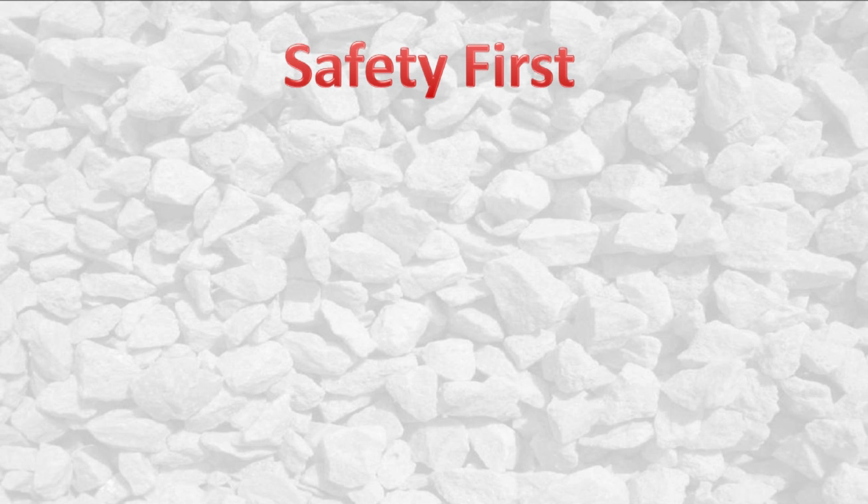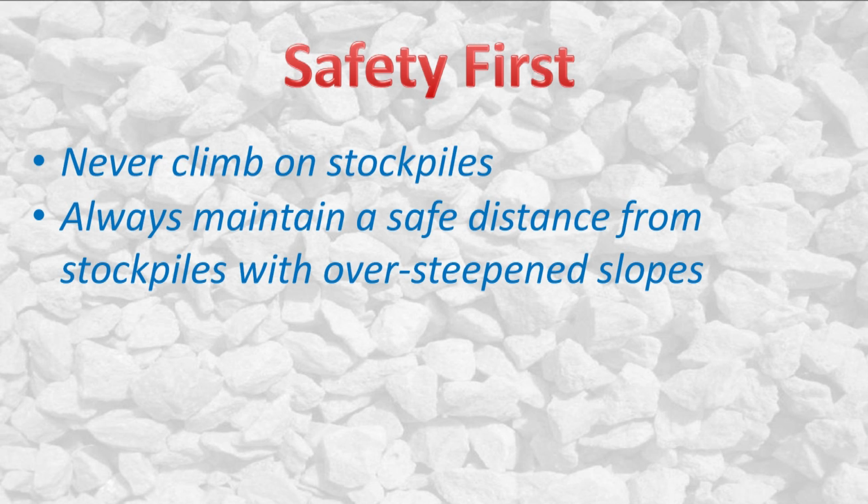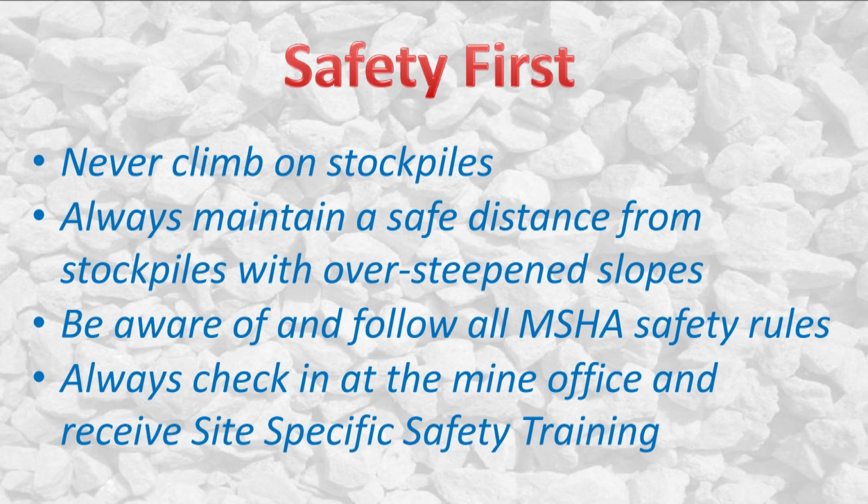Under no circumstances shall a technician ever obtain a sample by climbing onto the stockpile. Additionally, technicians shall always keep a safe distance from any stockpiles with over-steepened slopes. Aggregate sources fall under the jurisdiction of the Mine Safety and Health Administration, or MSHA, and are subject to very stringent safety rules. Please remember to check in at the mine office for specific safety instructions before continuing on to any mine property.